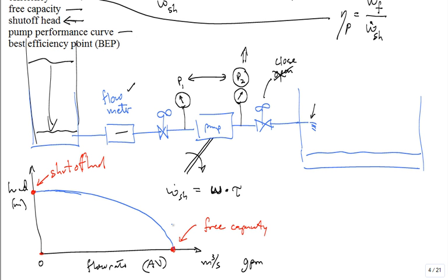And for every point of operation, I can calculate the efficiency of the pump. So we would measure the shaft power coming into the pump, and then we'd also measure what went into the fluid, which would be the head gain times rho g Q, something like that. Wouldn't that give me a good indication? It would be a product essentially of the head gain and the volumetric flow rate to get the power that went into the fluid. And you would divide that by the shaft power to drive the pump. That gives you the efficiency.